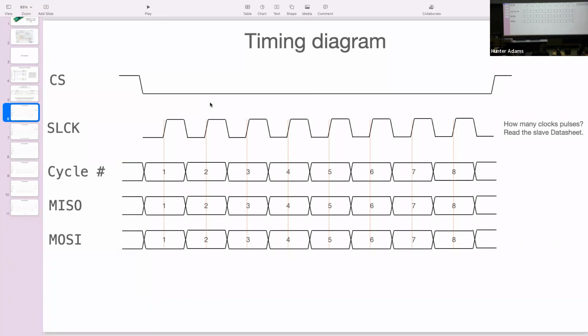In that CSDK function that we were looking at, which was setting a bunch of parameters associated with the SPI channel, it's those degrees of freedom, right? So you can configure the clock polarity: is the clock idle low, active high, or idle high, active low? And the clock phase: is the data valid on rising edges, or is the data valid on falling edges? In order to figure out which configurations you need to set, you find that information in the data sheet for the device that you're communicating with. I'll show you that in just a second for the DAC.